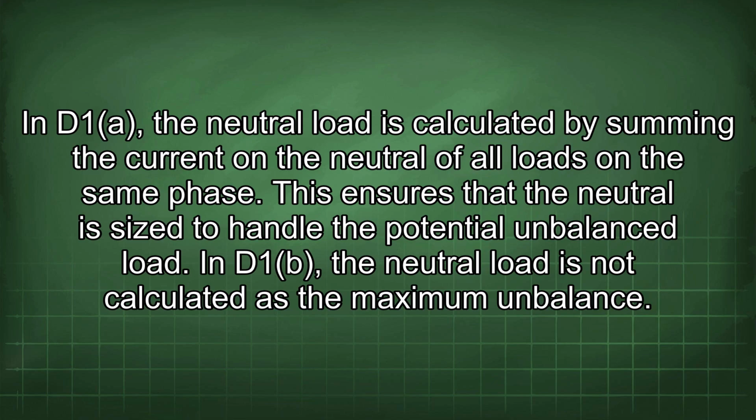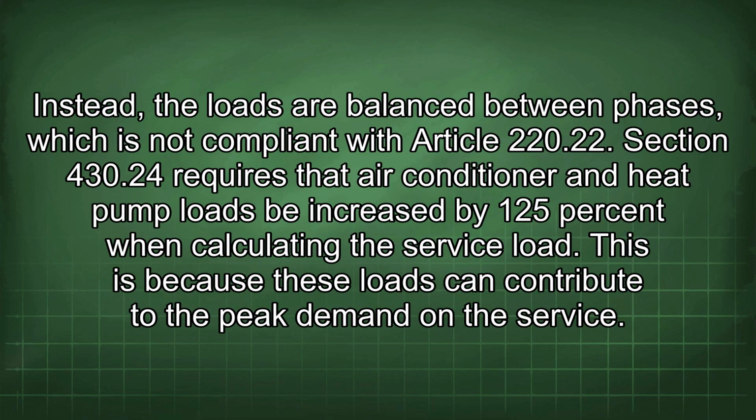In D1b, the neutral load is not calculated as the maximum imbalance. Instead, the loads are balanced between phases, which is not compliant with Article 220.22.